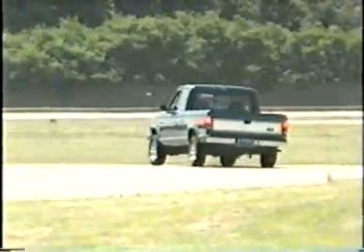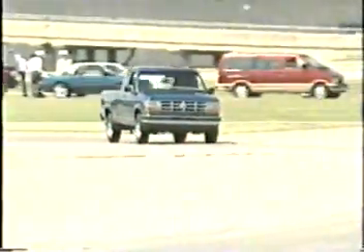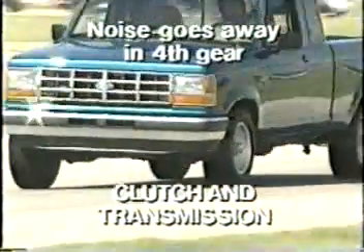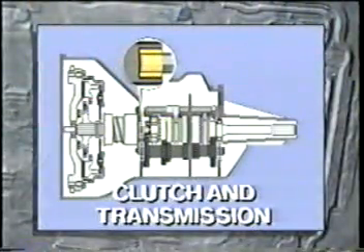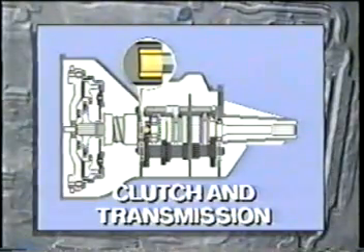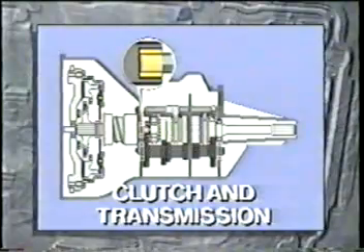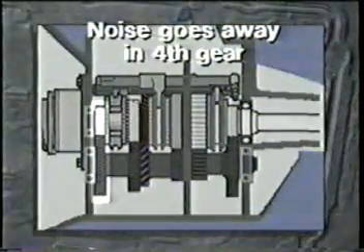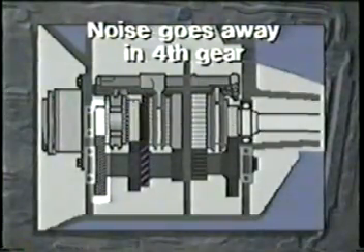In your test drive, accelerate and decelerate through all gears. If the noise goes away in fourth gear, the problem may be in the output shaft pilot bearing. This bearing is under load whenever the input shaft and output shaft are turning at different speeds. But in fourth gear, the two shafts are splined together and rotate at the same speed, taking the load off the output shaft pilot bearing. If the noise goes away in fourth gear, it may also be related to the input shaft and counter shaft drive gears. These gears are also not under load when the input and output shafts are splined together in fourth.